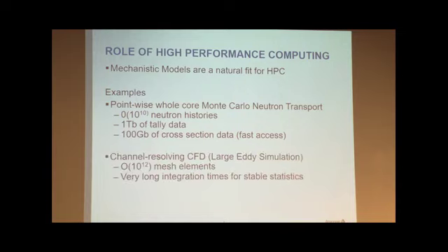Another would be channel resolving computational fluid dynamics, even something which is known as large eddy simulation, which adds a little modeling for the unresolved scales. So we're talking billions or more of mesh elements, very long integration times to be able to get stable or accurate estimates of statistical quantities. So immediately, when you recognize the scale of the computational problem for doing mechanistic modeling, it is tightly tied into both research and all of the techniques and knowledge that we've gained from high-performance computing.